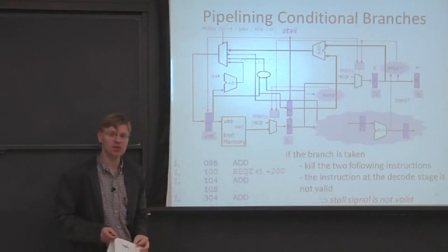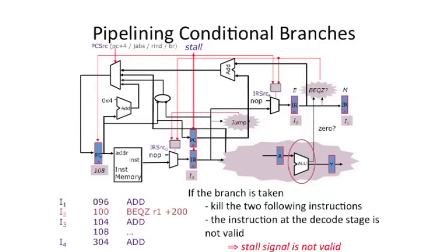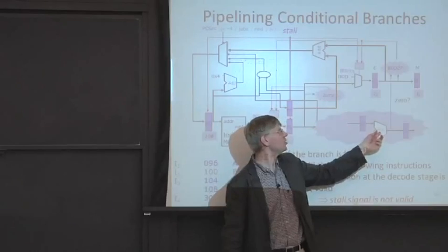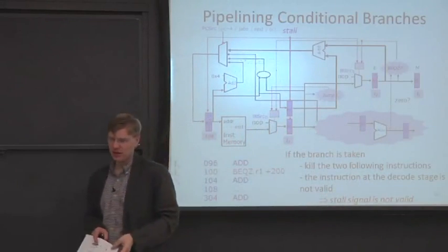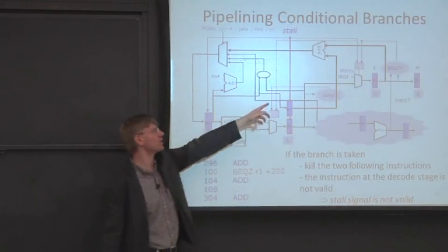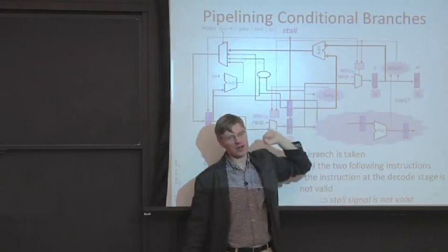Because on something like MIPS, there's PC relative branching. And the other thing is we can't reuse this ALU necessarily to do that. You could potentially reuse this ALU if you were microcoding your design. But unfortunately, we need this ALU to do the branch comparison. So we need to add another adder here to come up with the target of our branch.